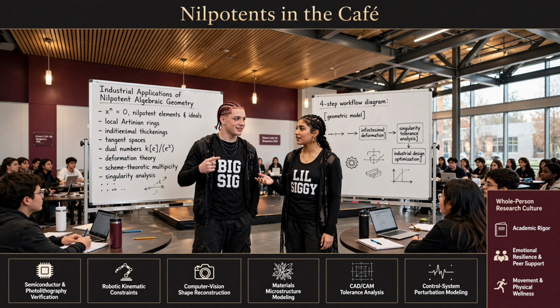So we inject the nilpotent cheat code, hyperdual numbers. Yes. By implementing hyperdual numbers, the process engineer writes the code for the base thermodynamic model just once. Just once. They feed the hyperdual variables into it, and in a single computational pass, the algorithm calculates the exact mixed second derivatives simultaneously.